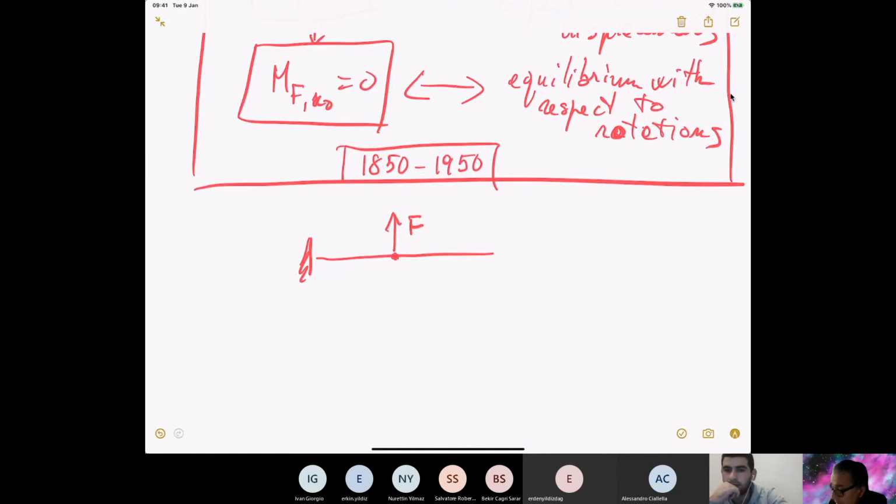Why can we talk about a concentrated force in the theory of beam? I tell you why. Because the deformation energy is given by this expression. So you have the second derivative of transverse displacement u appearing in the deformation energy.